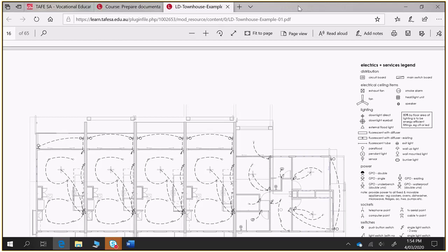you lock yourself into that. Say you say yes, we're using black butt, right? But then you might end up going spotted gum because there's a special on spotted gum and you can get it a lot cheaper. Chances are the council are never going to go, oh, that's spotted gum, not black butt. But technically, if you said it's going to be black butt, that's what you've got to put there for the council. As well as when you go to your insurer and you've got something that's not actually on the plan, all of a sudden you haven't created an insurance problem until such time as your house burns down and it was spotted gum, and that made no difference.